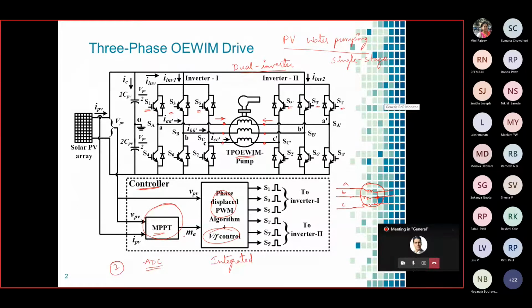The MPPT technique will define your modulation index for the PWM technique, and we can also give the DC link voltage we need for any PWM algorithm. So the DC link voltage as well as the modulation index is given to it, and then it is processed to generate these gating pulses, which should be given to the IO pins of your controller. These IO pins are generally named GPIOs, general purpose IOs, in the controller. The GPIOs will provide you dedicated EPWM pins. Generally a few controllers have only PWM pins, and a few controllers have EPWM pins.